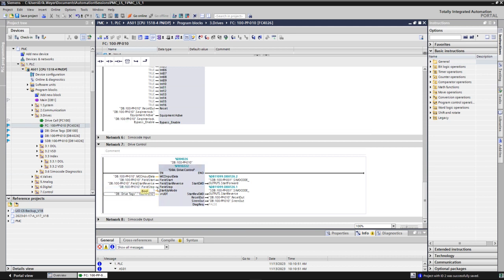There it is. One other configuration that we've got here is on the startup. My startup mode is when my block is scanned for the first cycle. Which mode do I want this block to start up in? I'm going to give it a 1 because I want it to start up in normal mode. I don't want it to start up in maintenance mode. And if I can just save my project.